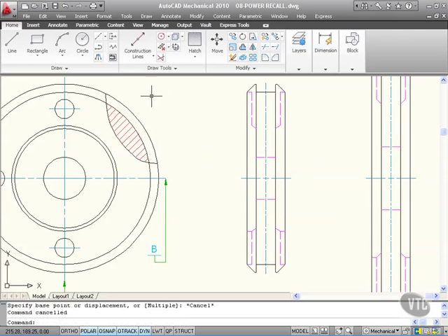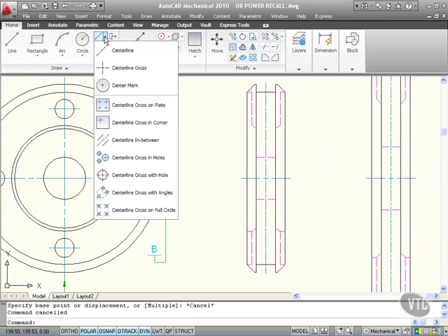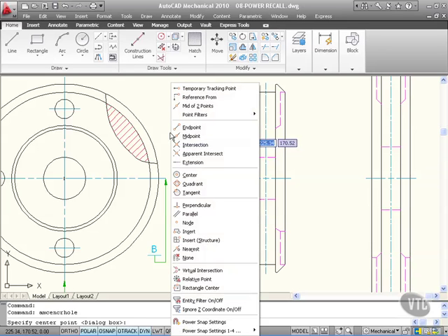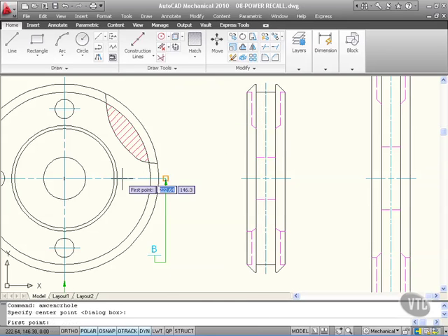So remember that when you're using these centerline commands, be careful, because it sometimes doesn't bring everything across. What it did there was basically recall the centerline command and not the centerline cross with the hole. That's AM center hole. All it's done is picked up on the object itself, the center line, not the circle. The circle is just a circle placed when you draw those center lines. So I would go back there and I'd do centerline cross with hole. I'd do a shift and a right click there, and I'd go for mid of 2 points, and look at the difference here. If I go quadrant, quadrant like that, line division